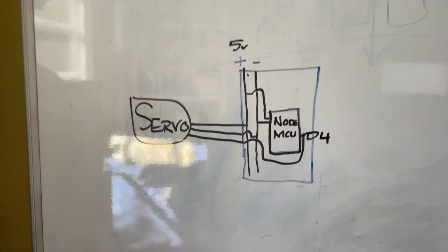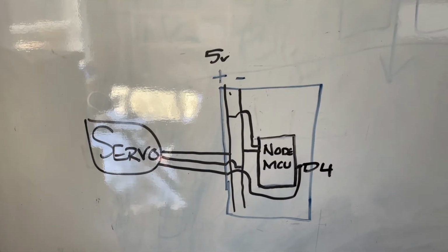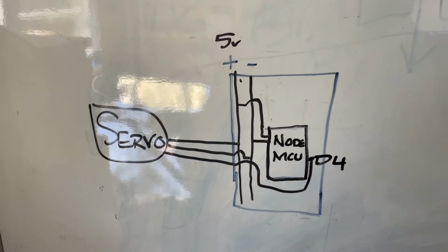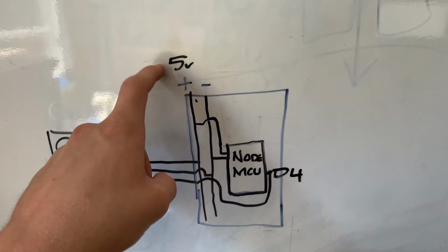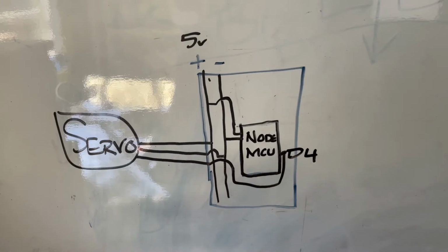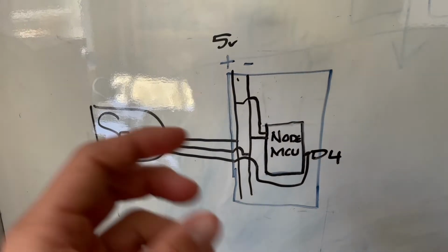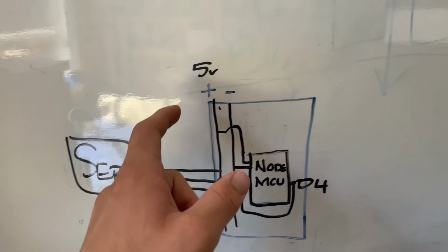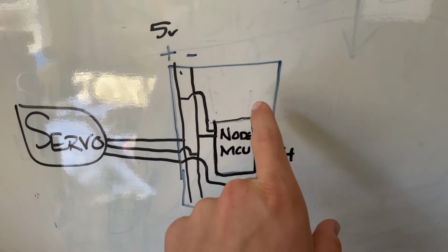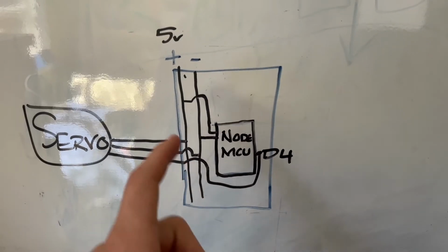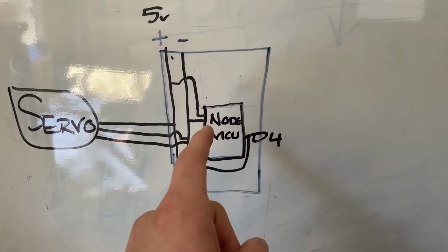Okay, so this diagram isn't great, but it'll give you an idea of how the circuit works. It's really quite simple. You have 5 volts. Most power blocks that you get for digital devices give out 5 volts. So I just have it literally plugged into my wall with a 5 volt Apple charger block. And then you just strip the wire and out come 2 wires. So 5 volts, the 5 volt rail. And then that powers the little mini computer, the NodeMCU. And so positive is connected to V in and the negative is connected to the ground.